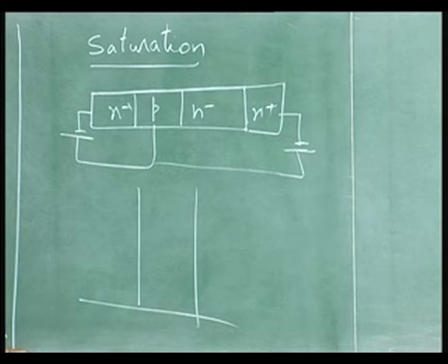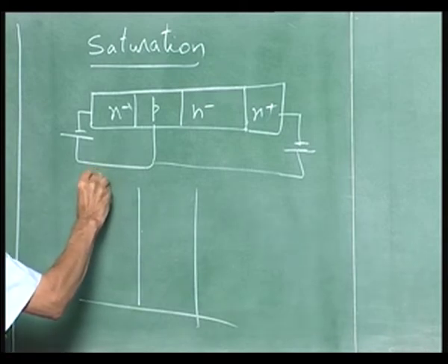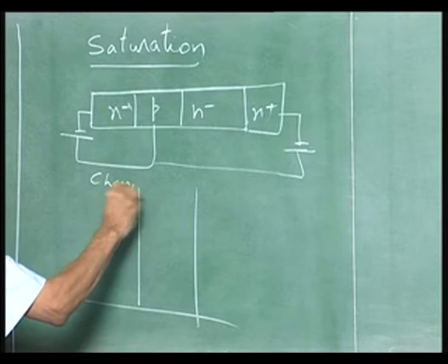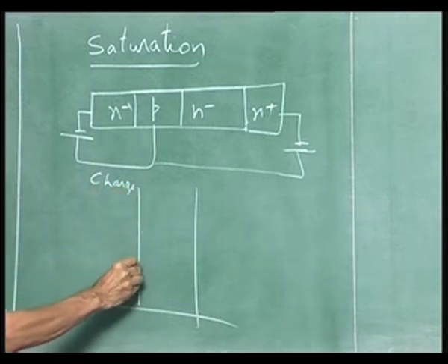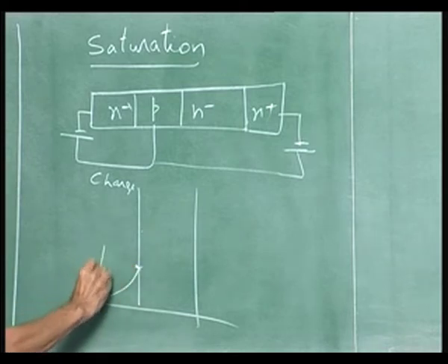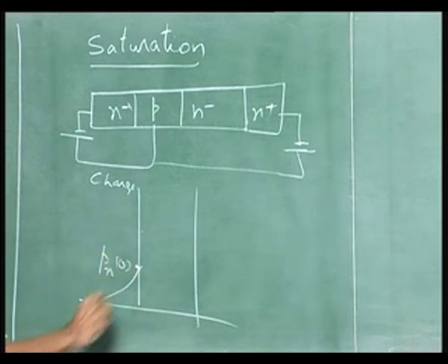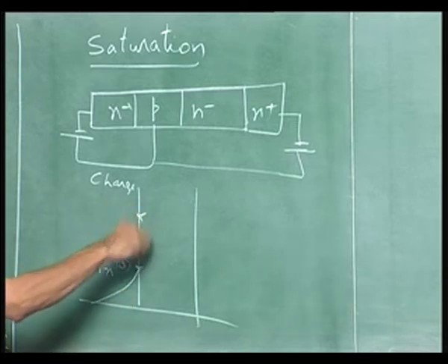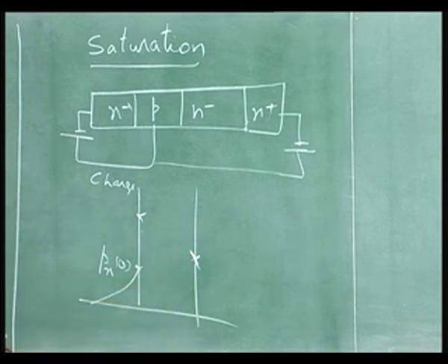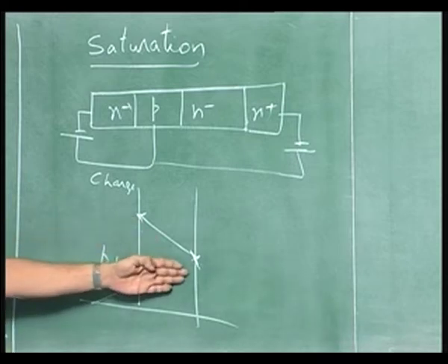That you remember when you go into discussions later, this is the carrier distribution, electrons and holes. Here that is like that. What about in the base? Collector is forward biased. Carrier concentration here is up, carrier concentration here is up. It is almost like that. In fact, if the base width is small, that is linear.